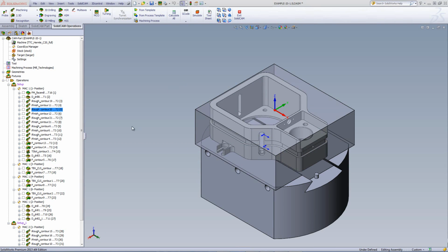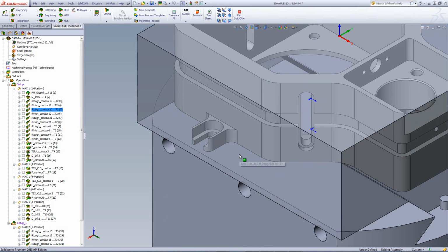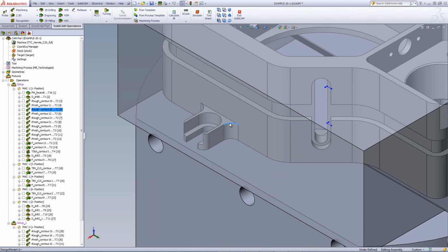Now I needed to complete the outside by milling down from this edge over here down to the very bottom over here. So for that, I've done another iMachining operation based on the first ones, just with different geometries and different levels.